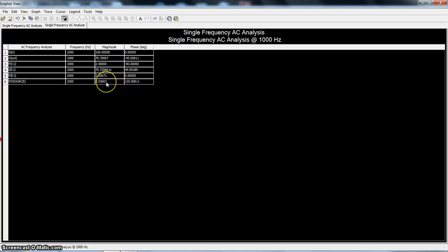So this puts it in the second quadrant, but when you consider that we are really dealing with power delivered, you switch it around, and it's in the fourth quadrant would be a positive real part and a negative imaginary part, and that would give you the appropriate values for the power dissipated and the reactive volt amperes stored in the capacitance. So this concludes this particular presentation on single frequency AC analysis.